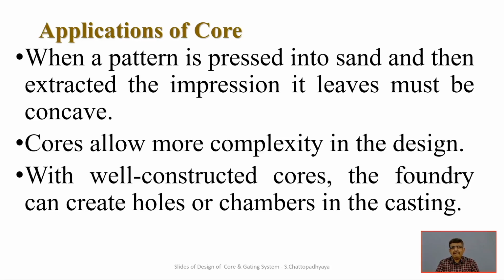Cores enable a casting person to go for very intricate designs, and in one go those complicated shapes will be there, where less machining has to be done. So wherever there are complexities and hollow sections, the core has a role to play. And with a well constructed, judiciously selected core, the foundry can create holes or chambers in the casting very easily, but their placement is very critical.